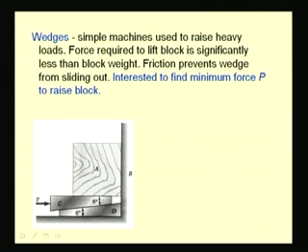A typical problem could be that we are interested to find the force P that a human has to apply in order to keep this block in this position or to raise this block. So, in order to analyze this problem, we have to consider the free body diagrams of the individual blocks and wedges and represent the frictional forces in proper sense. That means, we need to know the impending motion direction in order to draw these frictional forces in the free body diagram.